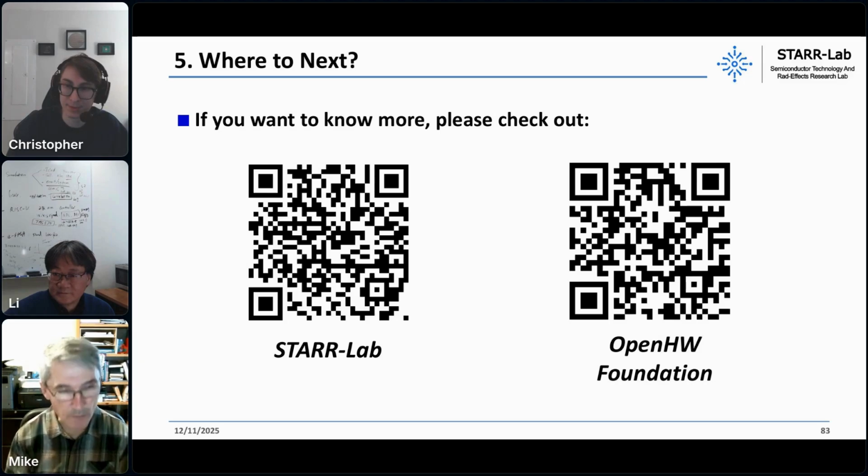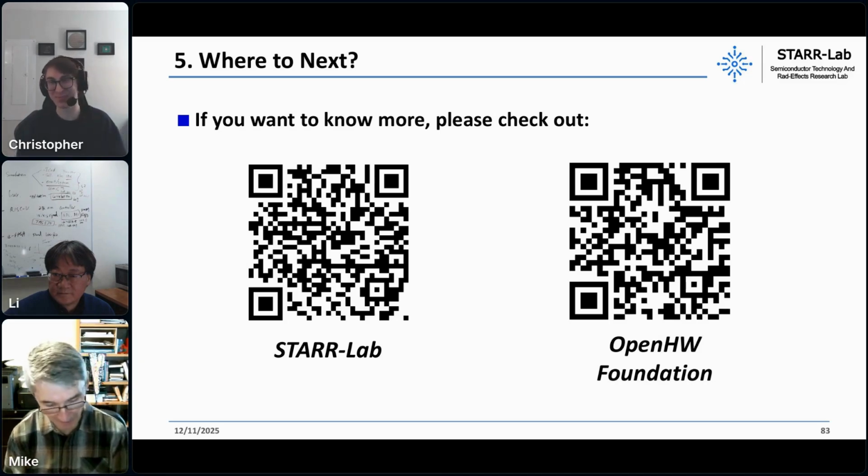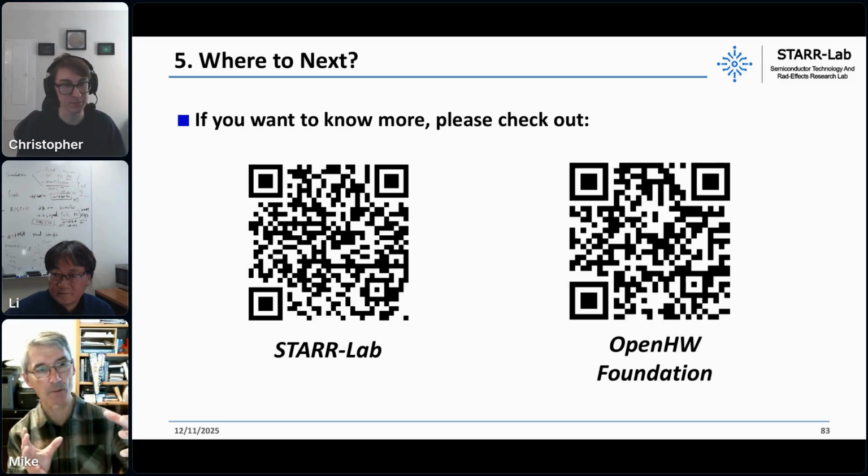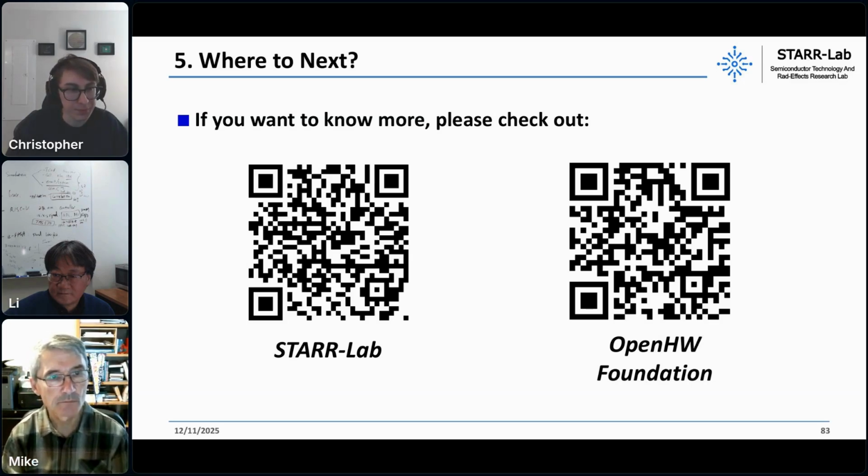This is a question that's come up before, but I think it would be of interest to this audience. Are you actually changing the GF22 FDX PDK? So you're coming up with those stacked transistors for the cells, so you're actually modifying the PDK to do that. Well, I wouldn't say that we're modifying the PDK, but we're modifying those standard cells that would be used in the place and route of the design.